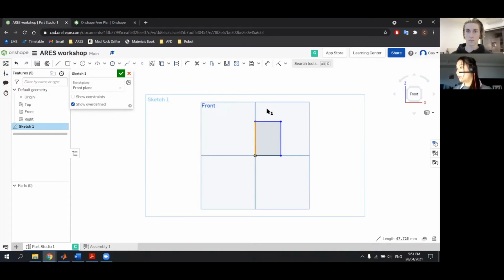It's a line that can be used to define axes and things like that. It won't appear in your sketch, but it can be used as a reference line. Say, for example, I want to draw a line here. I can select it, and then I can either press Q or click on this, and that will create my construction line, which can be treated like an axis.